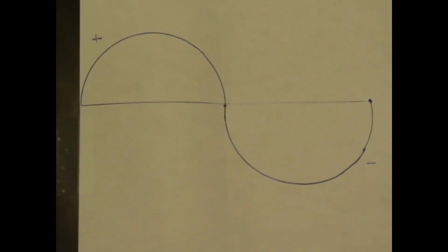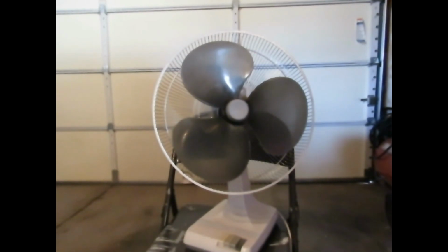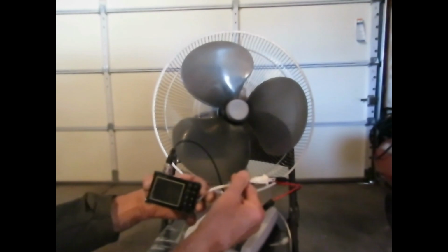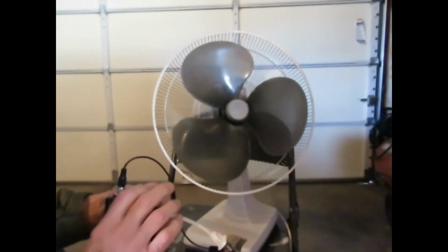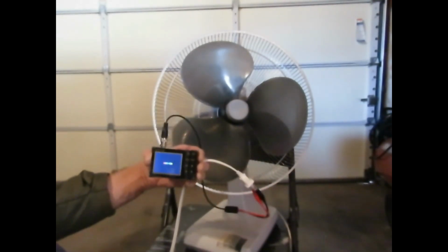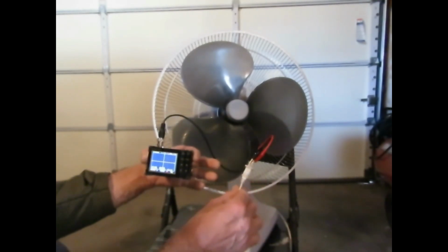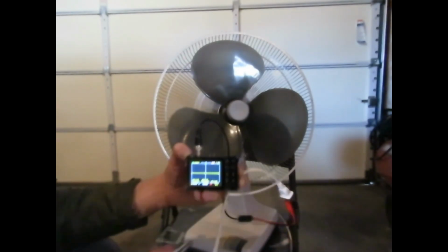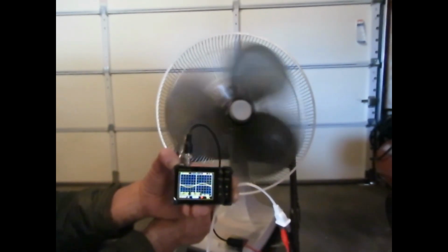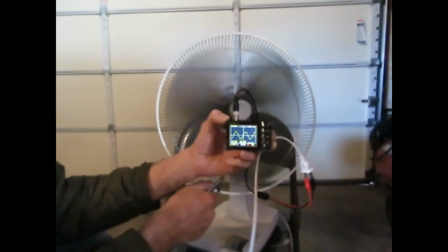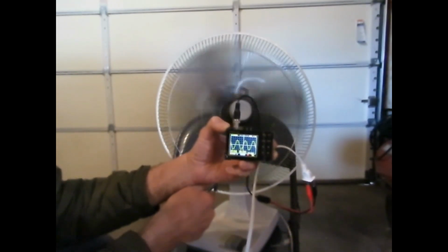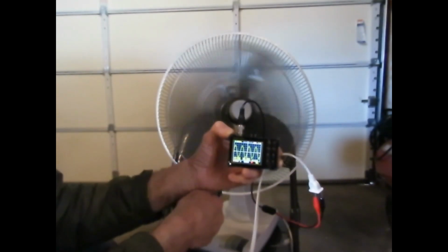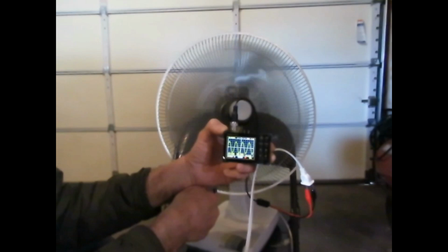Okay, we've reassembled the fan, and on it we have hooked up my oscilloscope to the electric cord with the two clips you see there on the prongs of the electrical cord. And we'll use an air compressor, an air hose, to generate electricity by blowing the air in the fan and spinning it. The faster it spins, the higher the frequency of the sine wave becomes. You see it scrunch together as it's sped up. And if we hold it there, it'll stay.